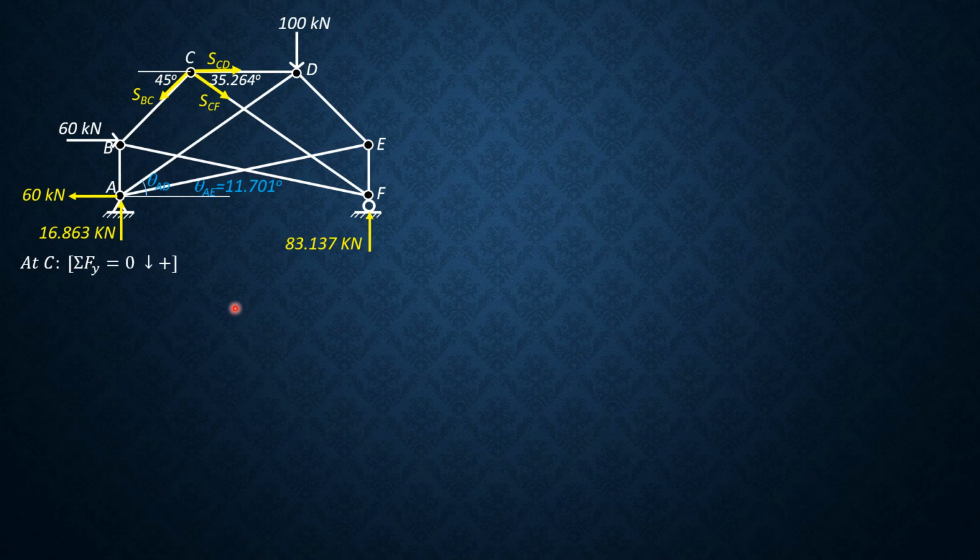So SCF sine of 35.264 plus SBC sine of 45 degrees equals 0. Then SBC is equal to negative 0.81649 of SCF.